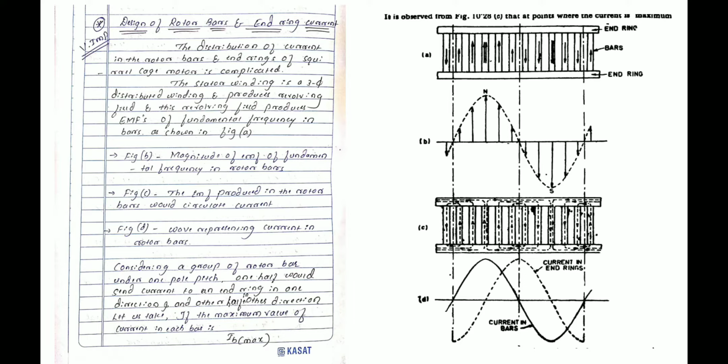Keep it in mind. So the stator winding is provided with the 3-phase alternating supply, and this winding is of which kind? Distributed type. The distributed type means the conductors are placed under several slots and the number of conductors will be equal, and that is the reason this kind of winding usually reduces the armature reaction and also helps in better cooling.